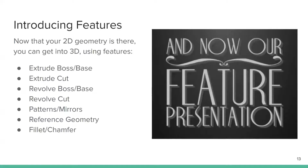So some different things you could do with it would be to extrude boss base it. That's the name of one of the tools that essentially takes it and extrudes it outward into 3D space. So if you applied that to your rectangle, it would turn it into a block. Well, I guess our rectangle's a square, so it would be a cube.